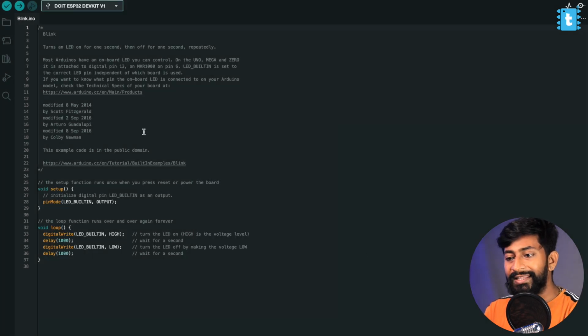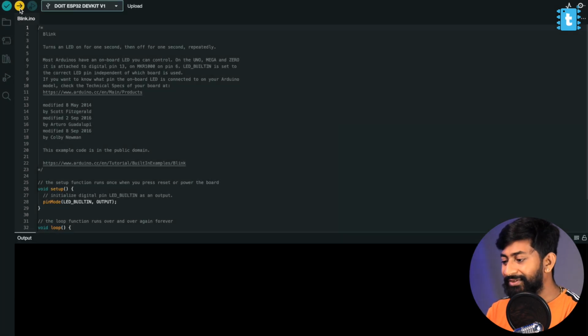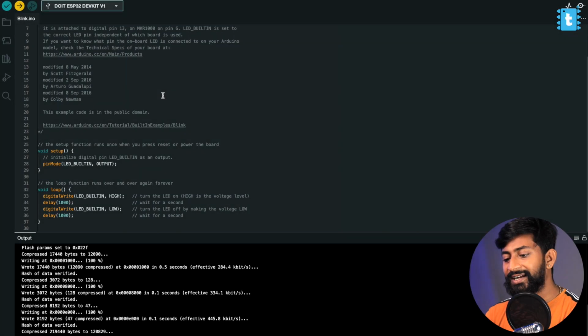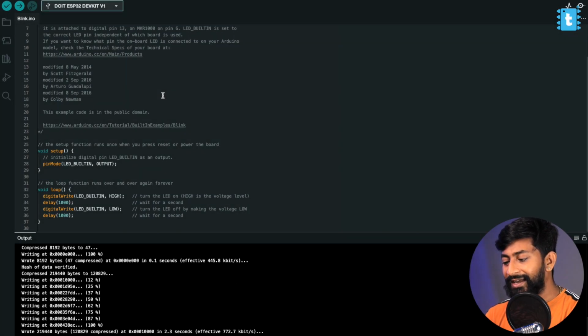Now we are good to go to hit the upload button. So I just hit the upload button and wait for the sketch to get uploaded. It started uploading the code onto this board. And the code is successfully uploaded and the LED started blinking on it. I don't know if you're able to see it or not, but it is blinking. You can trust me. So it is very simple.